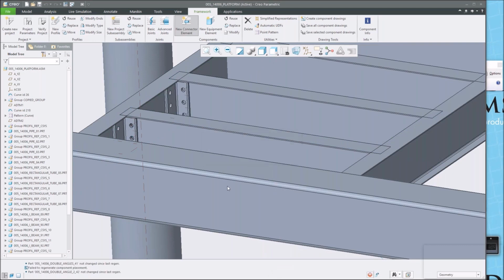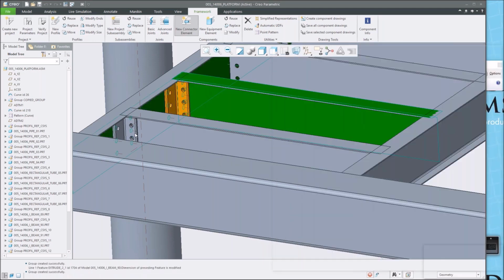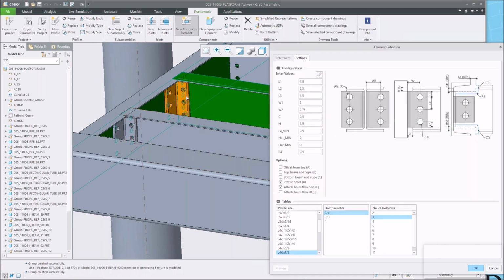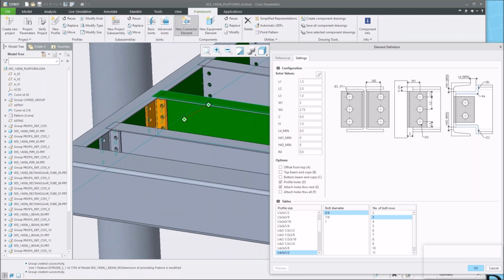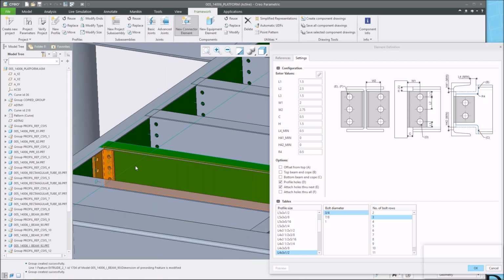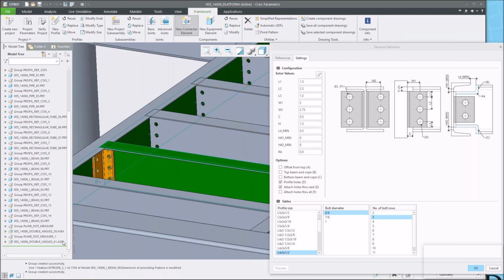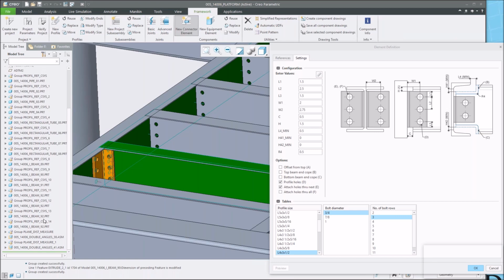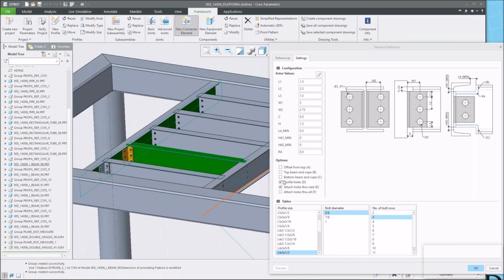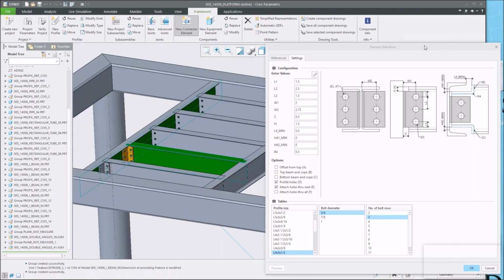Now you'll see something a little bit different here that you didn't see before. Not just on this beam, but on the subsequent beams after it, the holes are also there. The reason is that we basically said this is the same part. So in our model tree, those are actually all 92s. Whenever I put holes in this one, it automatically propagates the holes to the subsequent beams, because it is the same one. Great. I'll select OK.